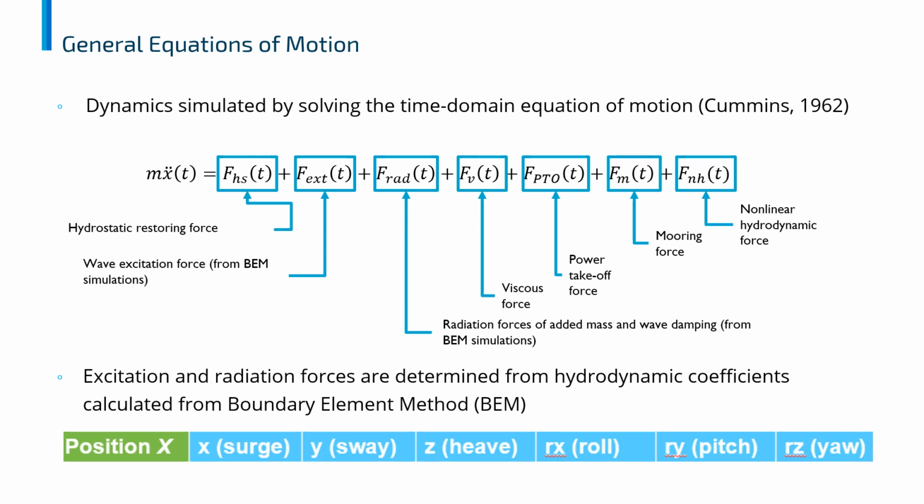Now that the WEC-Sim code workflow has been defined, we want to make sure that users understand the theory behind WEC-Sim. WEC-Sim uses the time domain equation of motion following the Cummins formulation to solve the dynamics. The equation shown here is the general equation of motion, where mass times acceleration is equal to various external forces. These include the hydrostatic restoring forces, wave excitation forces, which are obtained from boundary element method solvers, radiation forces,